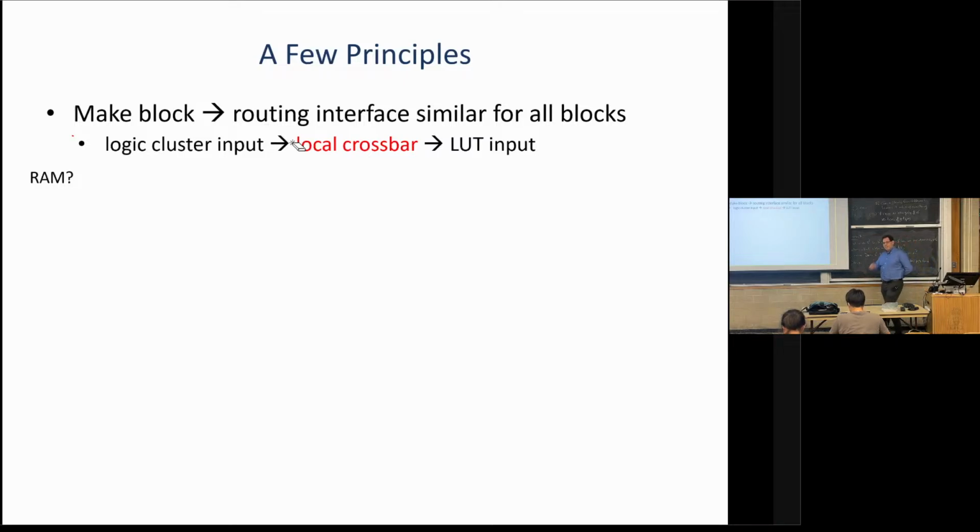Yeah. So you may still want to have some amount of permutability among your inputs, though, which you do get from the local crossbar. Okay, so you're agreeing that it's not as useful for capturing outputs feeding back to inputs, but you're saying I still want it. Yeah, well, I still think it would be useful for permutability among your inputs. Right, and I was actually trying to lead you guys down one path, right? But Isidore's refusing to be led down that path, so kudos to his intellectual strength. So Isidore is saying, well, yeah, despite that, and also fan out is not as common either in a RAM, right? So in logic blocks, I might have some enable signal that goes to all the LUTs. In a RAM, it's unlikely I'm going to take some data bit and say, I'll write it in all the RAMs.